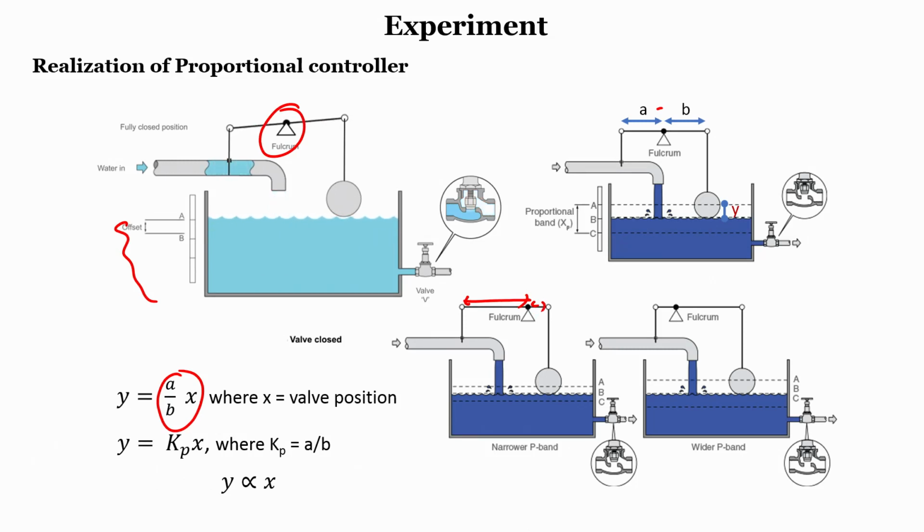So, when the bob is at a low position, more input flows in, that means the valve will be completely open, so more water flows into the system. The band, if you see, will be completely narrow. When the flow keeps increasing, there is a sudden close, a sudden stop of your input. So, this error band depends entirely on the gain, on where exactly you place the fulcrum.